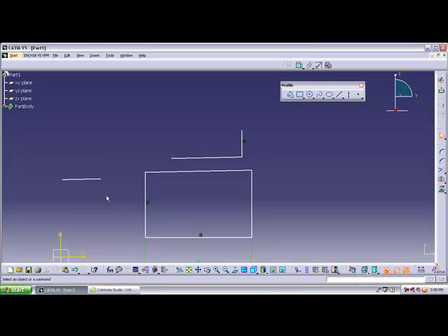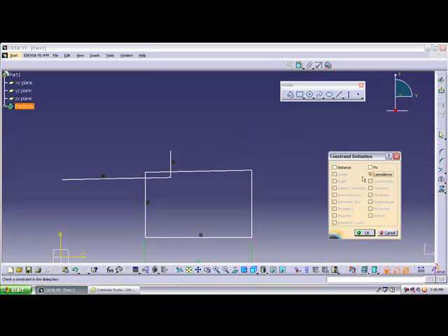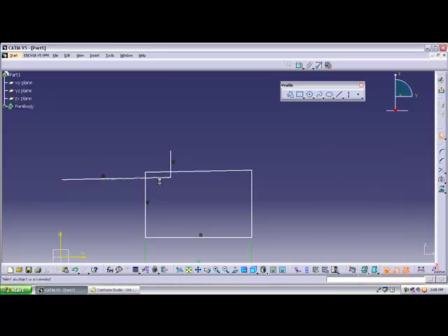now we made the two axes coincident, but not only axes, we can also make two points coincident. It means there is no path for points, but by making two points coincident, what will happen? It means we are joining the two points. Okay, applying coincidence to two points is nothing but joining. By holding the control button I am selecting the two points, selecting the geometric constraints, and I am applying the coincidence. See what happened right now. See, the two lines are coincident, which means the two points are joined.